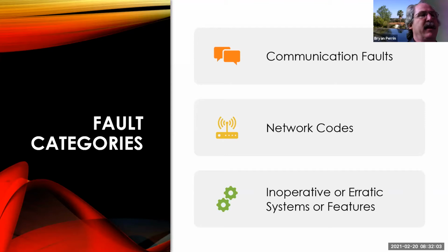So every communication problem has to do with the scan tool. However, many diagnostic solutions involve the scan tool retrieving codes that report problems between modules. Is the code set because the scan tool connected? Some networks only work when you talk to a scan tool. Do I have codes, and I clear the code and it's a hard code, but yet I can talk to everybody in the network? Why is that?